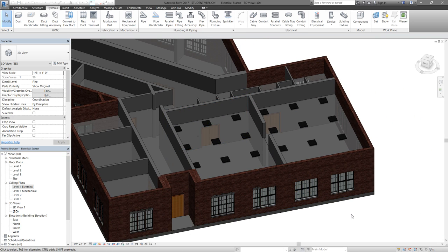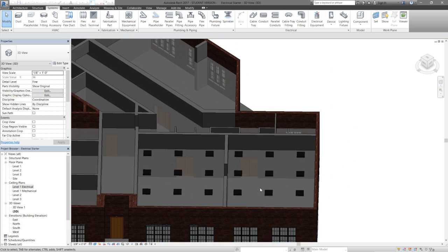If you have lights in a room and your lux value is not changing, so say I have 12 lights like this in my room but my lux is still 0, double check that your lights are facing the right direction. They might just be facing upwards.